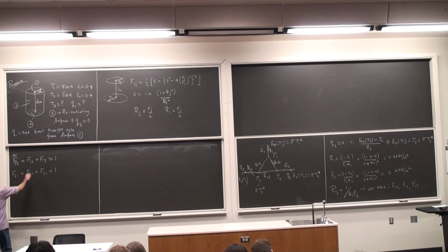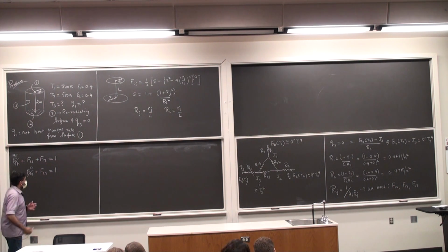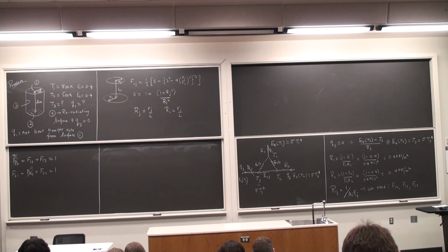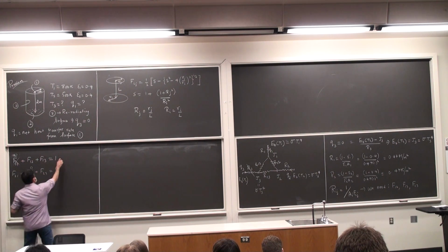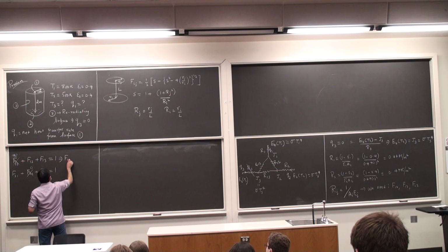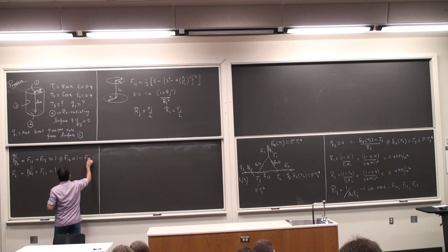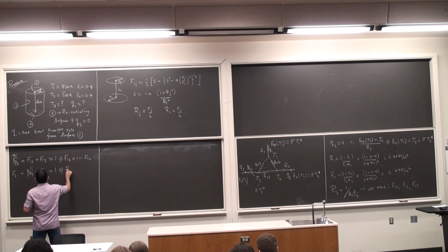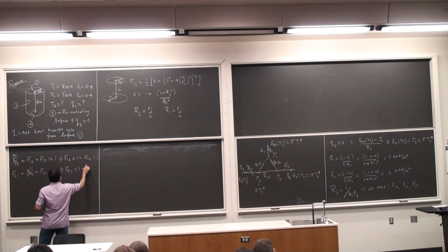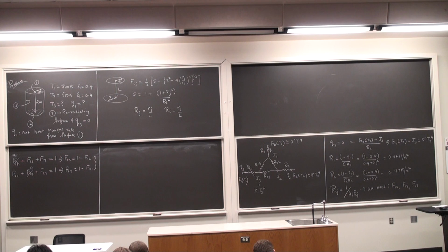F22 is also 0. There is no harm done if you write it for the third surface too, but it's not of much use to us. So the aim is if I can calculate F12, I can calculate F13. And likewise, F23 is 1 minus F21. And I need all of these to calculate the geometric resistances Rij.